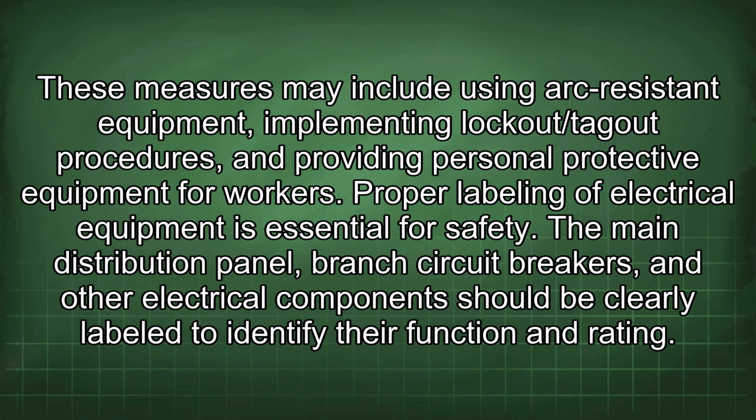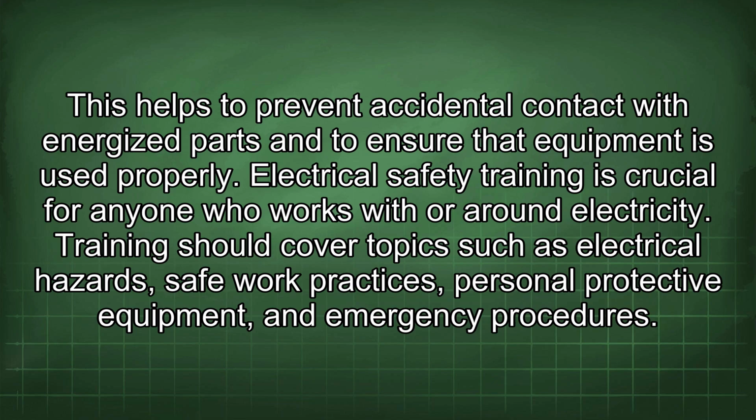Proper labeling of electrical equipment is essential for safety. The main distribution panel, branch circuit breakers, and other electrical components should be clearly labeled to identify their function and rating. This helps to prevent accidental contact with energized parts and to ensure that equipment is used properly.